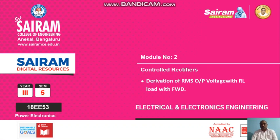As we understood, using the freewheeling diode across the RL load prevents the reduction of the DC output voltage. Due to the presence of an inductance, the DC output voltage decreases. To prevent that, we should connect the freewheeling diode across the RL load so that the reduction in the DC output voltage can be controlled. In this session, we are going to discuss how to derive the expression of the RMS output voltage with the RL load with the freewheeling diode.